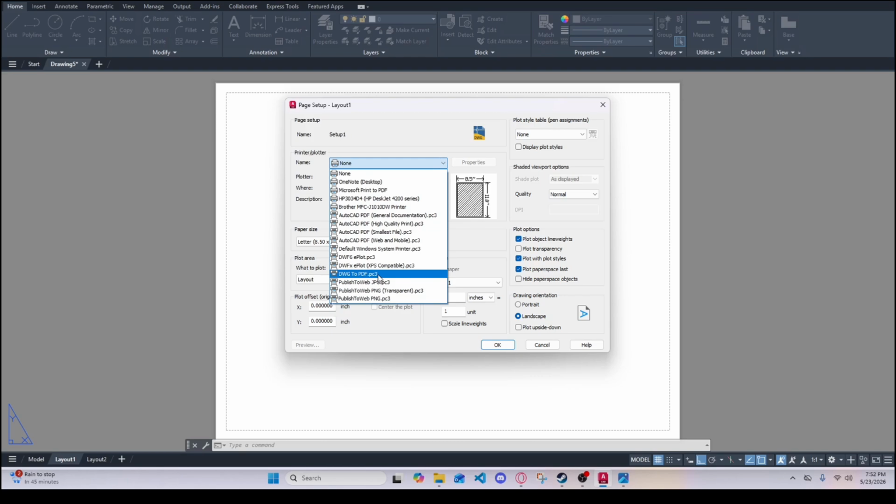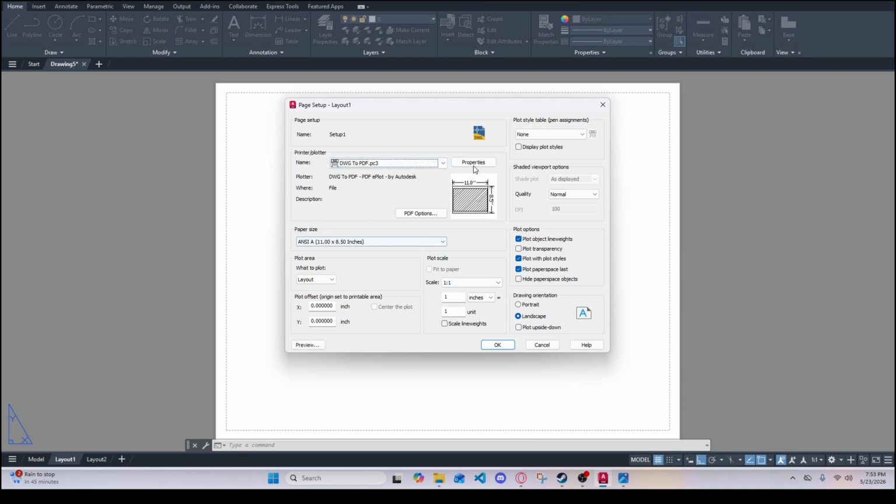Let's say you share the PDF with somebody through email or whatever, they can go ahead and import that PDF and literally convert it back to DWG, which you can do up here in this insert tab, where you can import PDF. If you just turn your drawing into a regular PDF, they wouldn't be able to do that. I'm pretty sure there are ways to do it, but for the sake of this, let's go ahead and do Draw into PDF. And then it'll give you this preview of the paper size you're going to be using.